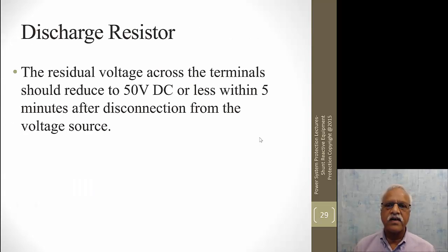So when you look at the discharge resistor, it essentially discharges the capacitor when you disconnect it. There are trapped charges, so you want to make sure that the voltage is less than 50 volts DC in 5 minutes. So the discharge resistor is rated accordingly by the manufacturers.